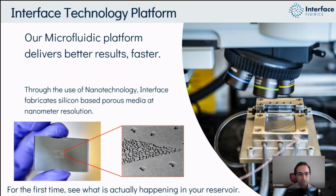In terms of the operations, we design and fabricate synthetic porous media on our silicon substrate. Once everything is finalized, we do the experiments using the reservoir fluids. During the process, we use our optical platform to visualize the fluid flow in the porous media and probe the interactions and fluid behavior at reservoir relevant pressure and temperatures.